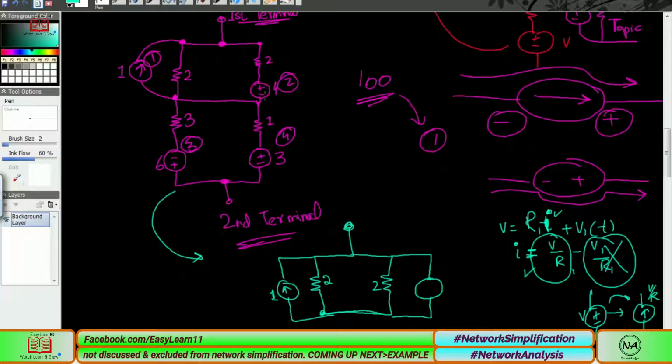First thing, always keep in mind that the polarity never changes. I mean that if we have the positive on the upper side, then when we convert this into a current source, make sure its polarity is like this one, because we are not going to change the current source in such a way that it disturbs the whole network. If you choose the wrong side, then make sure you correct it. Because the positive is on the upper side, its arrow will be like this.